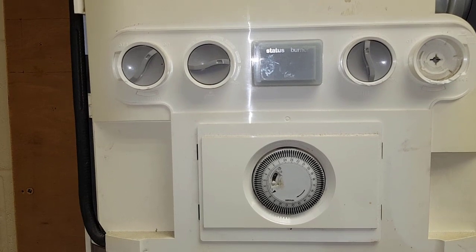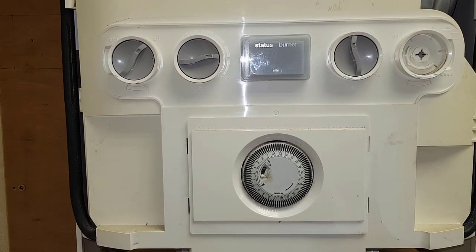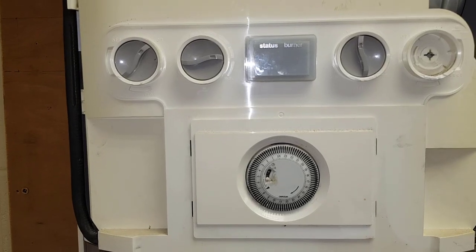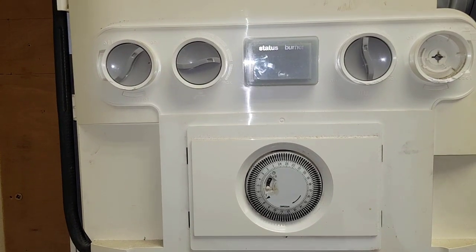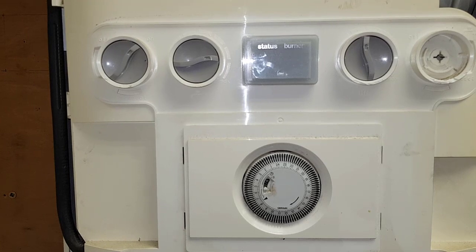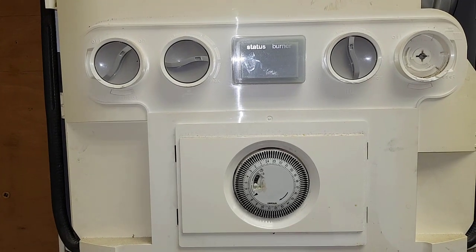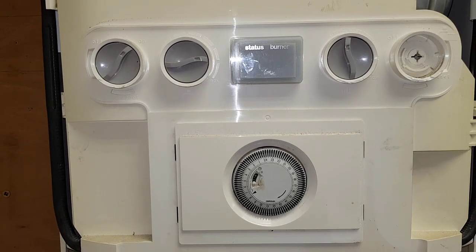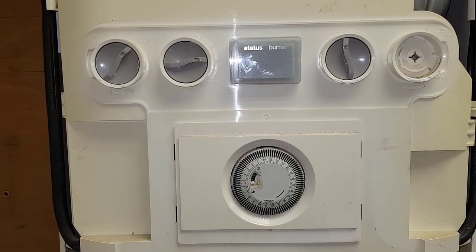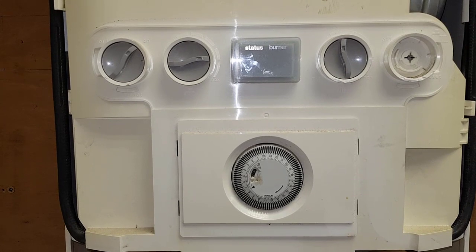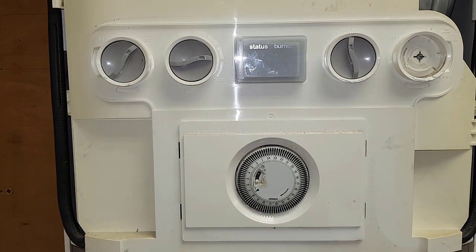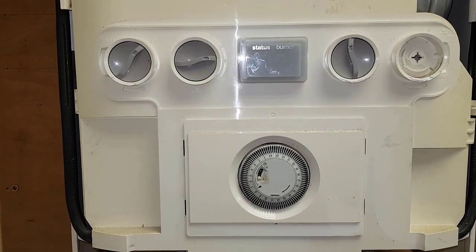So you've got to make sure the isolation valves are in the correct position, because it's going to cut off the flow or return. The boiler can't circulate, gets hot and shuts down straight away. So you simply make sure the valves are in the correct position before you go on to the next step. It's as simple as that.